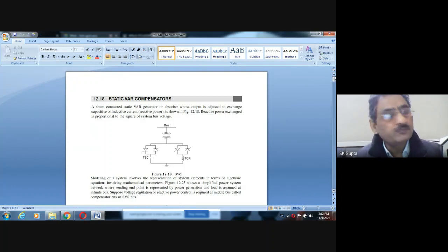Earlier, while performing the power flow analysis, we assumed that since the role of AVR is to maintain the constant voltage, and it does so by supplying or absorbing the reactive power, it controls the voltage of the system. So in the conventional method, we used to assume it as a PV bus.